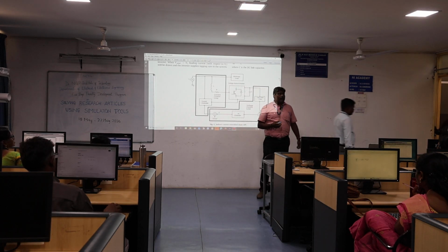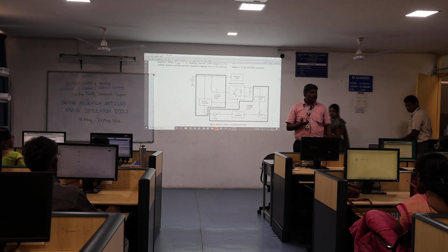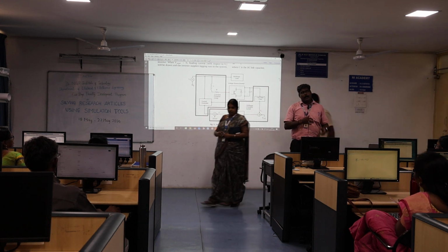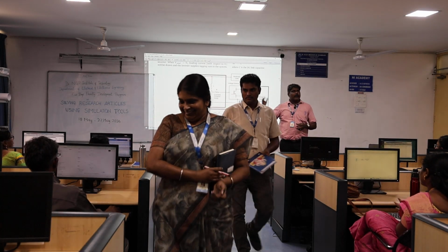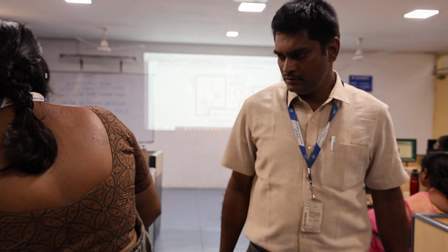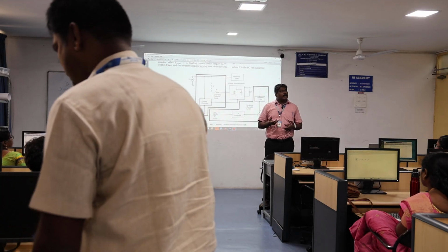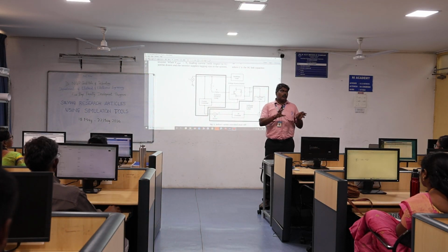You can use a diode rectifier. Diode rectifier is also one of the examples of non-linear load. Or after the diode rectifier, you can connect some inverter, then the inverter connected maybe to some induction motor drives. It is applicable for electric traction application also. In electric traction also, we need to improve our power factor, or we need to focus on the power quality. We can also use this type of devices.